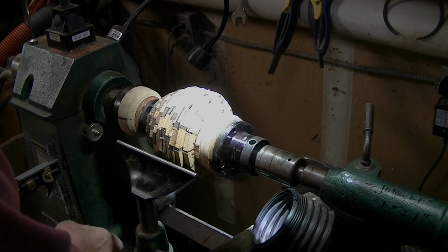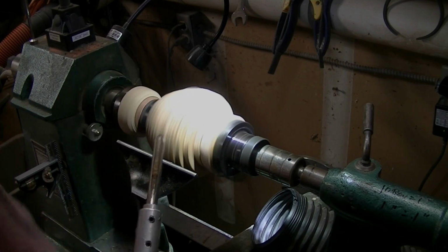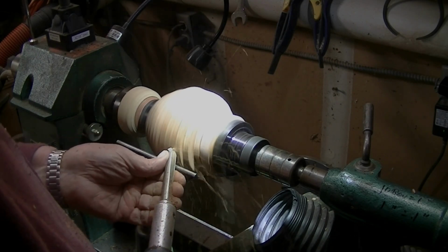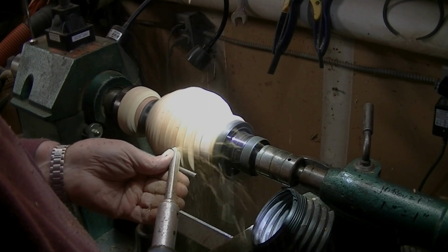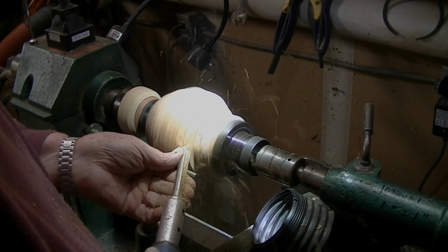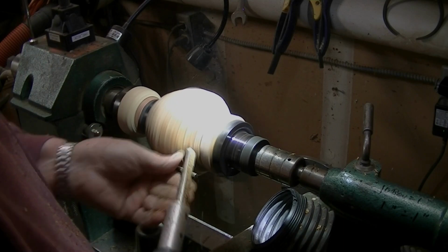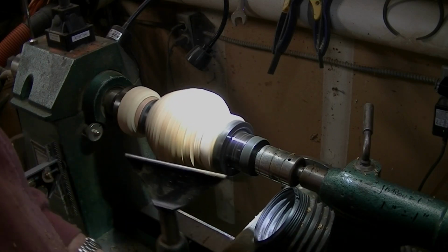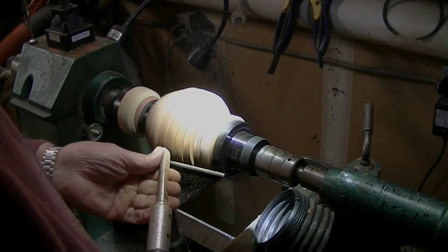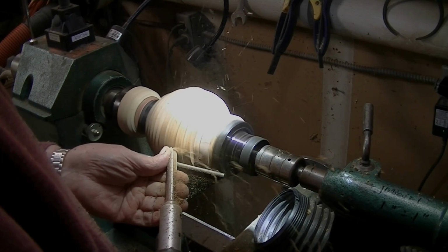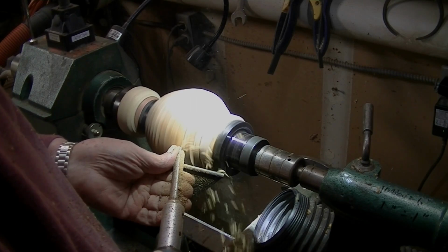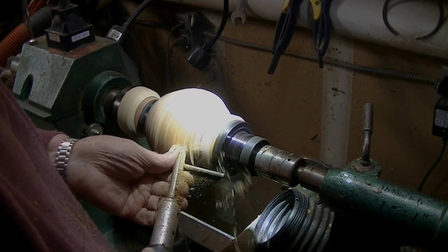And with my bowl gouge, I'm going to begin to roughly shape the exterior. First of all, just knocking off the corners of each of these rings and beginning to pull them into the rough shape. The top of the vessel has a small curve in it, and so we're trying to pull that curve in, that reverse curve, right near the neck of the vessel. We'll try to get the exterior as perfect as we can before we do the inside.